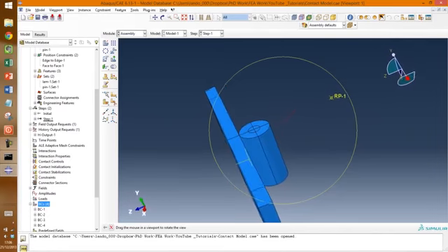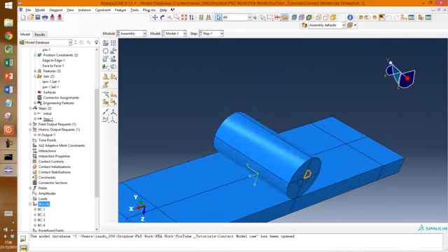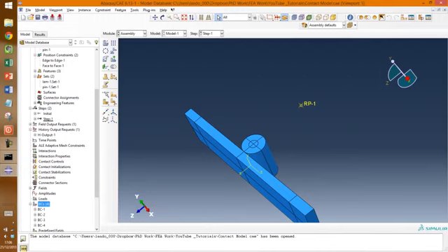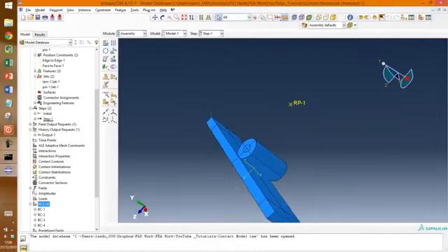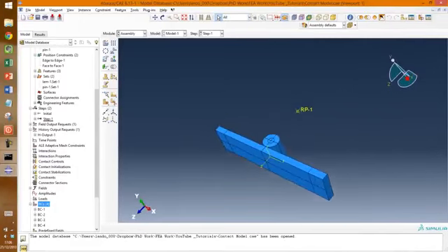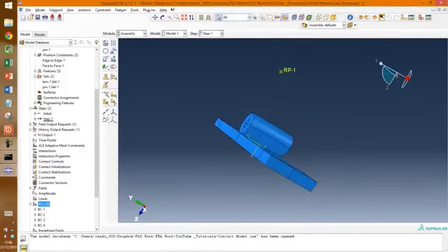So essentially what I'm going to do here is define a relationship between that point and the base of the loading pin. So basically if you tell that point to move 3.5 millimeters in this direction, the loading pin will do the exact same. And I can extract load displacement data from this. So it'll tell me the force that manifests itself on this pin as I'm loading by that certain displacement. And it's just a neat way of doing it. So I have this put in place.